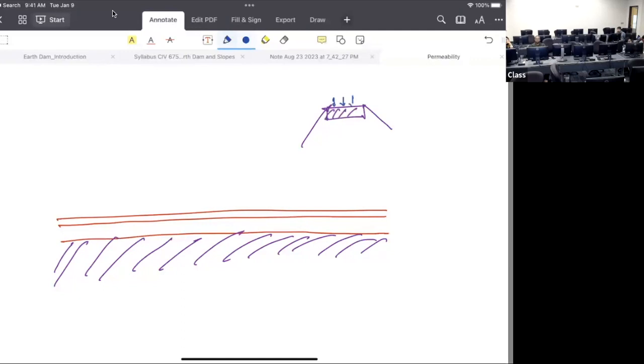You have the water, right? Water comes in, infiltrates the subgrade, and then over a period of time, it will create a wet area. Right? Basically, you're creating a bathtub here. Because underneath, again, your permeability is very, very low. Right? So underneath, your permeability is very, very low in the soil.